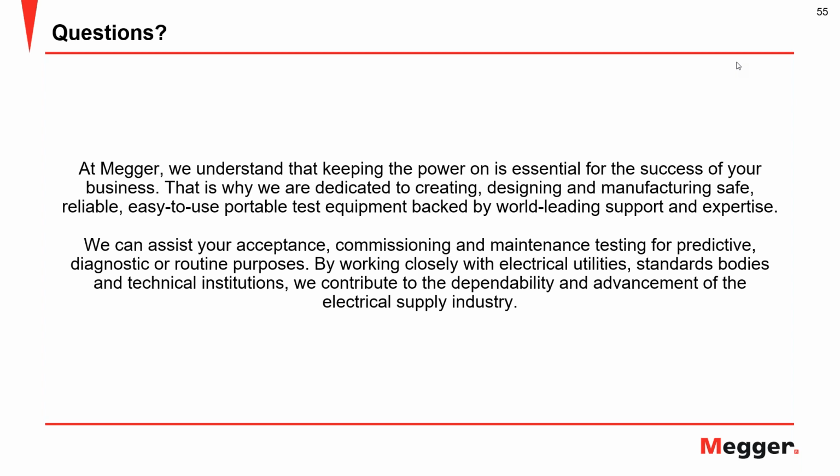Let me start with this. We know from decades of experience, and I don't just say Megger, there are other companies as well, the utility companies, the service companies. If you have a defect in accessories, this is in the hundreds of picocoulombs, in the thousands of picocoulombs. I just showed you an example from a real cable during the presentation. So there's no doubt that you will see it.